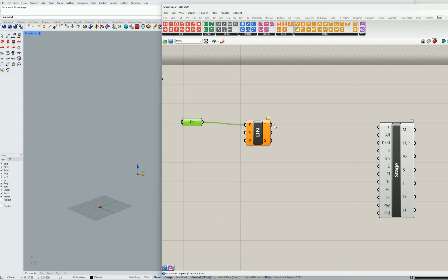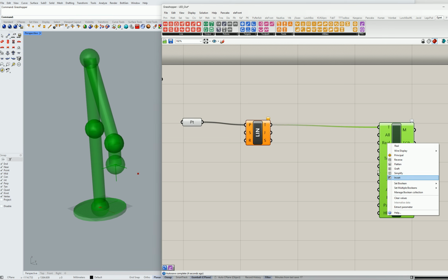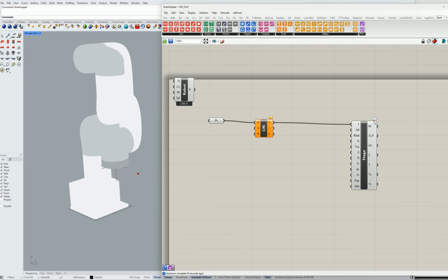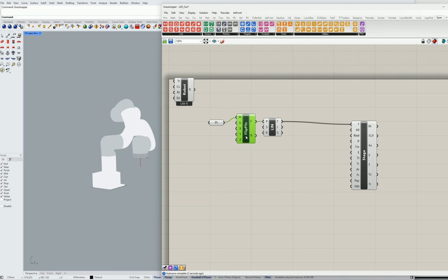I am going to get an error here. Let's switch this to the real view of the robot. Cool. You see we get a singularity issue. Why is this? Because you can see the Z is facing up in the Z positive direction and our effector is facing down. So the robot is going to try approaching it from underneath. It's a quick fix. We can just flip the plane. And now our robot goes to that point.